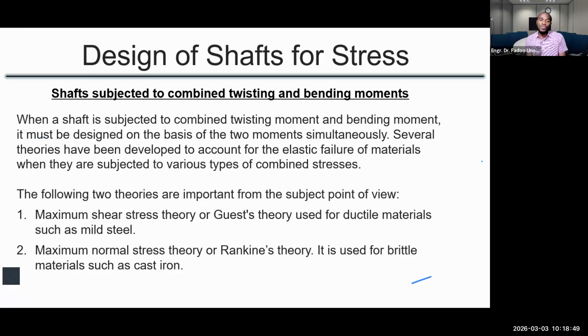If you look at Shigley, you'll find very complex equations, and so we're still going to stick with these for now. So two theories that we will employ in this class are the maximum shear stress theory, or what is called Guest's theory, which is primarily applied to materials that are ductile in nature.